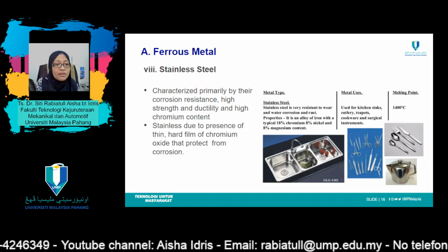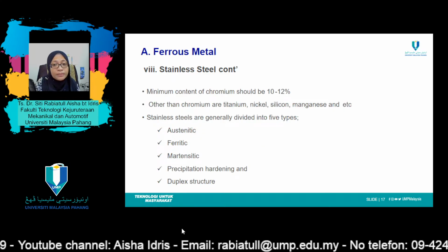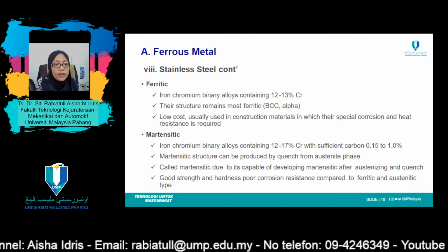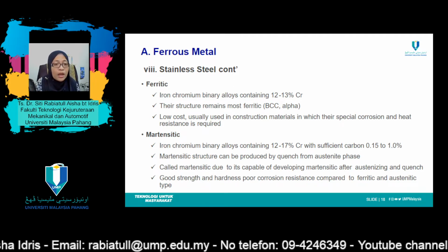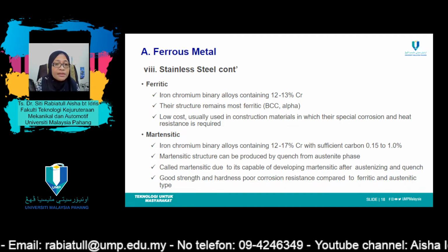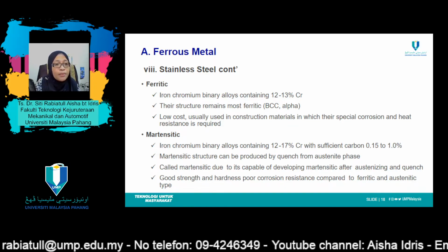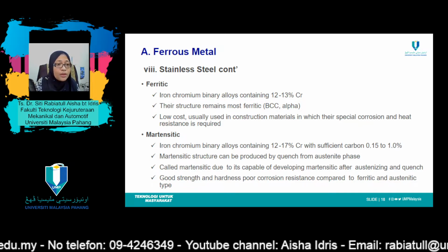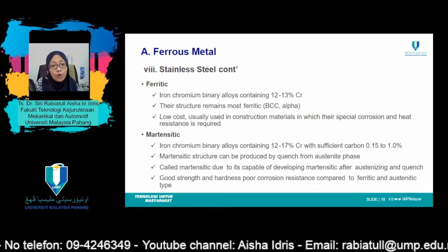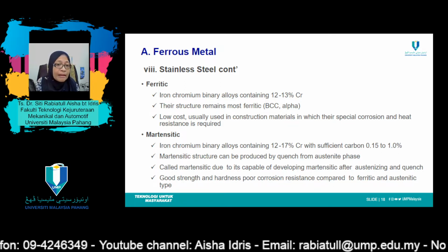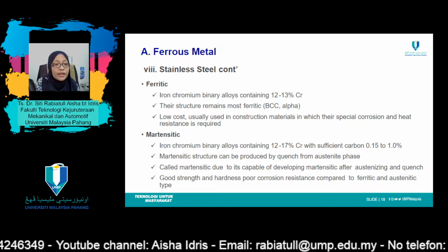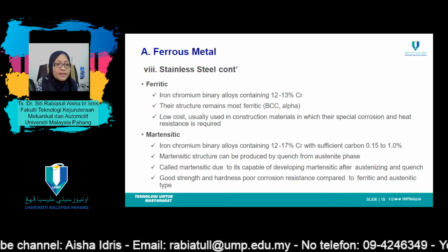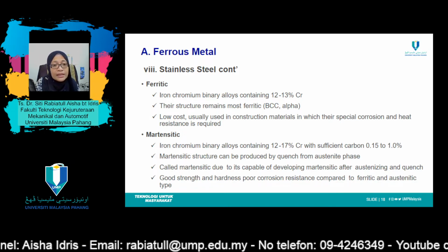Ferritic stainless steels are composed of the alpha ferrite phase. The austenitic and ferritic stainless steels are hardened and strengthened by cold work because they are not heat treatable. The austenitic stainless steels are the most corrosion resistant because of high chromium contents and also high nickel additions, whereby they are produced in the largest quantities. Both martensitic and ferritic stainless steels are magnetic. The austenitic stainless steels are not.